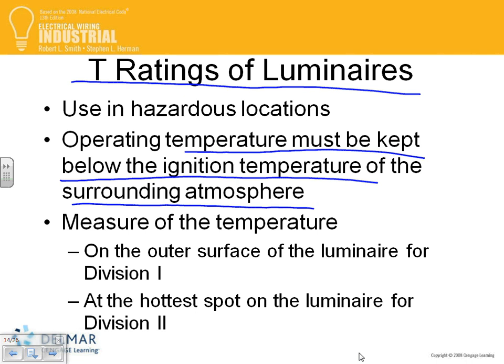Okay, here's how they measure them. We care less about how they measure them; the manufacturers do a lot. In Div 1 locations they go by the outer surface, and in Div 2 locations by the hottest spot. That's how they rate them. Any questions, guys, about the T rating?